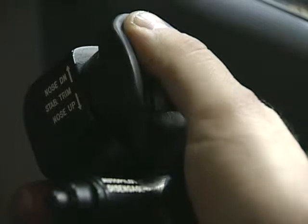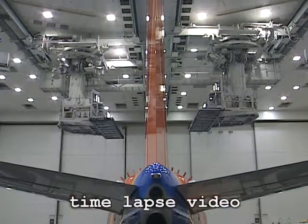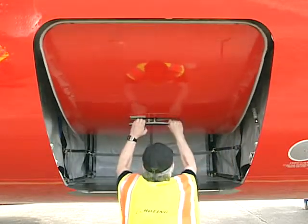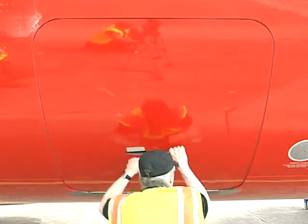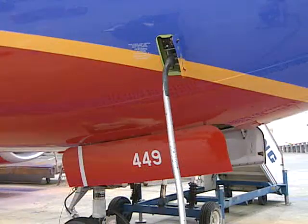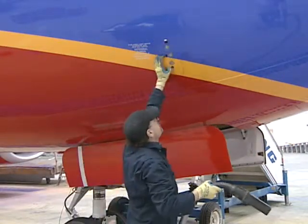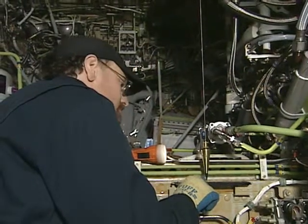Set the horizontal stabilizer to its neutral position. Close all passenger and cargo doors and move all seat backs to their upright positions. Remove any exterior lines attached to the airplane. Finally, check that the airplane is level.